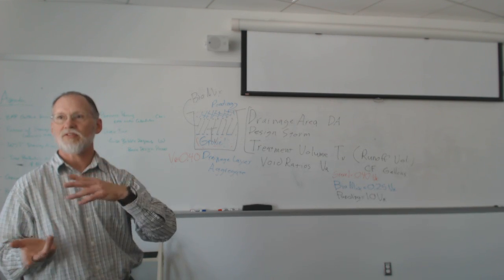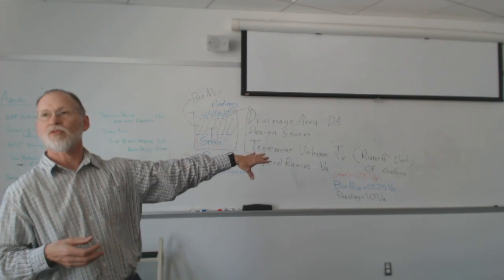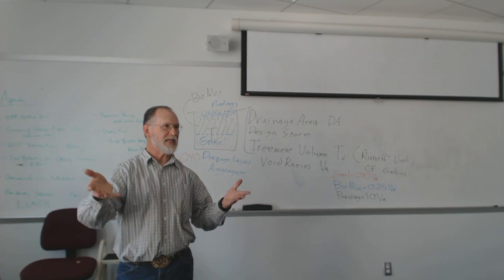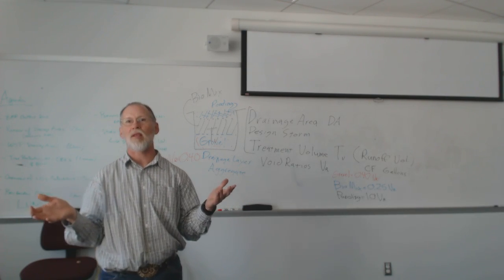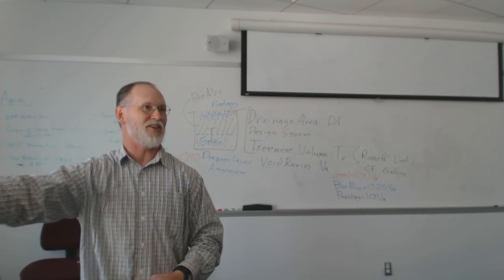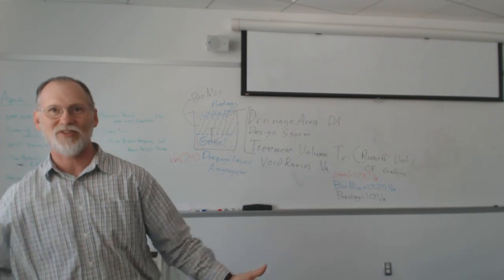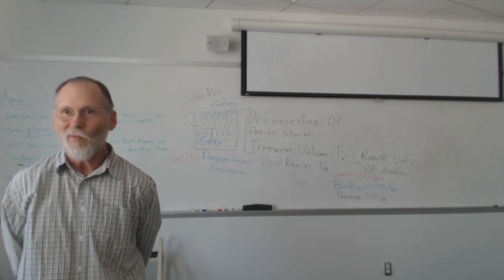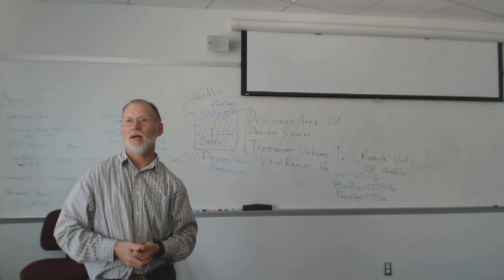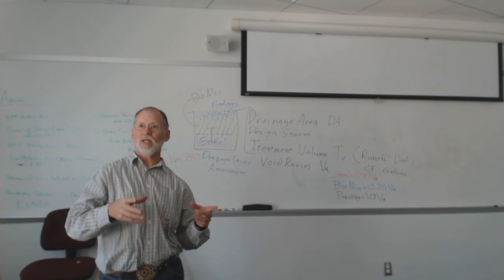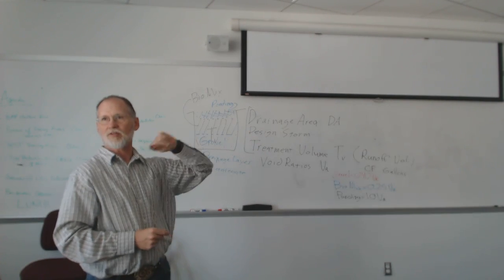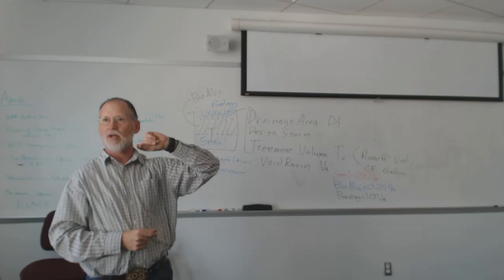Right. So if you design this with overflow piping, like the ones I just did for these River Smart schools, DC is the only place, I think, in the entire planet that requires a 15-year storm. Lots of luck. All that data on the NOAA site, they don't even do a 15-year storm. So basically you go to DC and ask what they consider a 15-year storm. Here's the magic number, and you plug that number in. But that storm is really just about the overflow structure, so the rain gardens fill up. I'll touch on that as I get into the rain garden design.